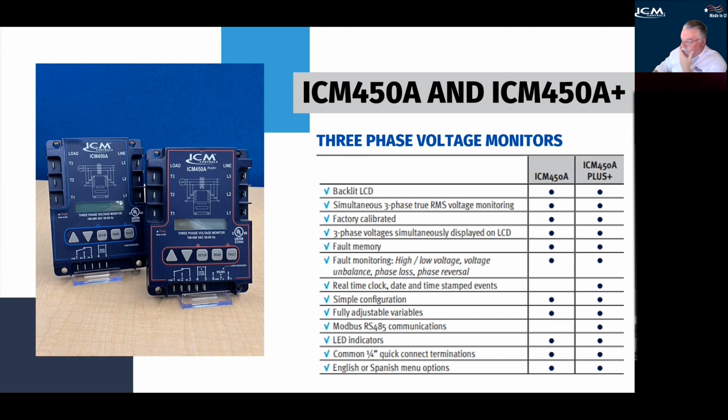And we changed the connection terminals to these quick connect terminals, like a spade terminal. So you can put an insulated spade terminal in there. A couple of different things can happen. First of all, you can reach in there with the screw type terminals and get bit by electricity if you're not careful. But you can also short some things out if you're not careful with those open exposed terminals. So this is a safety feature and just problem solver, kind of a headache solver.